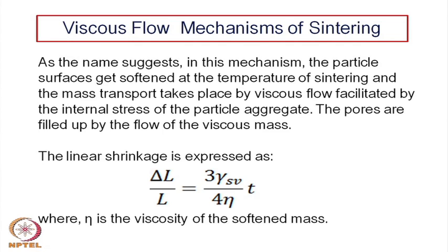The linear shrinkage is expressed in this manner. Once again, there is a temperature and time dependence, and it is in fact linearly dependent on time in this case. And the term which is more important here is the viscosity. So far we have not talked about the viscosity of the solid, because it was basically solid state diffusion or an evaporation kind of mechanism.